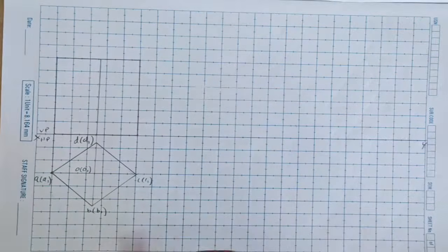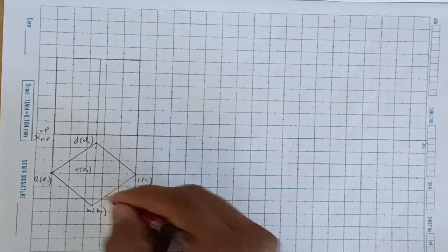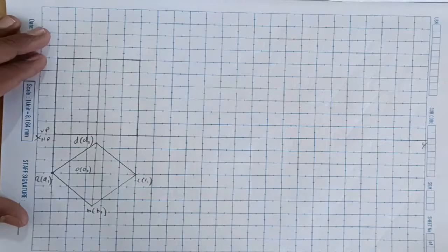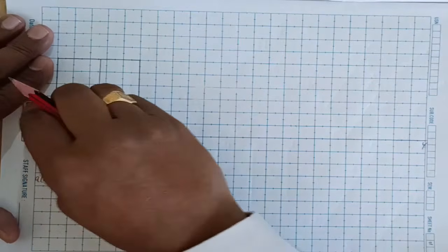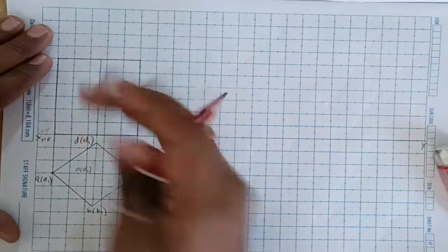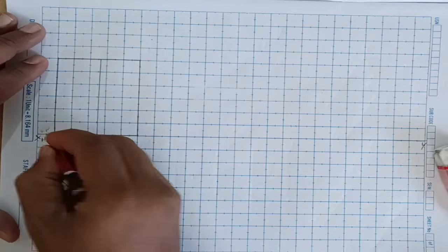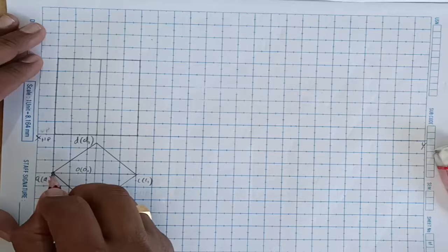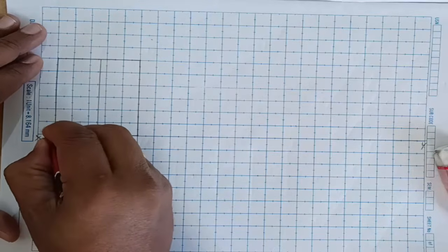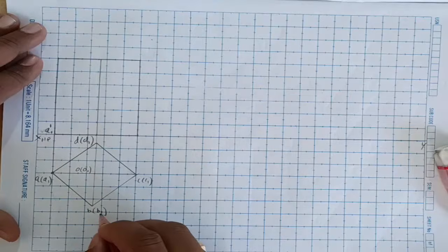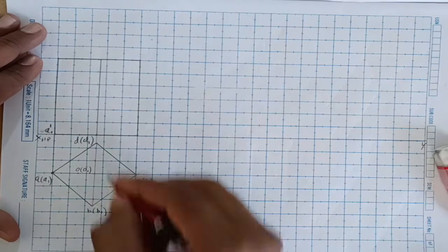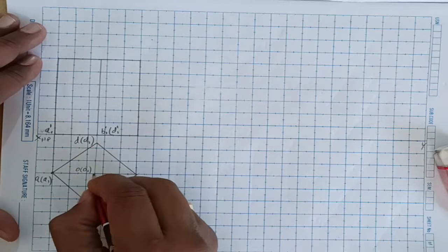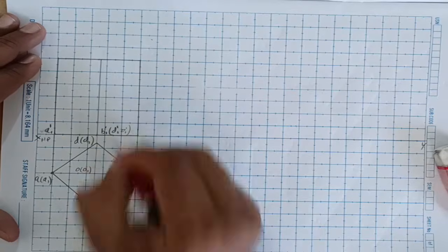In the corner condition, the axis line overlaps with these edges, so there is no need to draw the axis line; it overlaps inside. Coming to the naming: this point is A at the top and A1 at the bottom, and B1, C1 at the bottom and ABCD at the top. At the bottom here, only one corner, A1, is here, so we name it A1 dash. Here B1 and D1 are there, B1 coming first, so we name it B1 dash, D1 dash, and the center also, O1 dash.